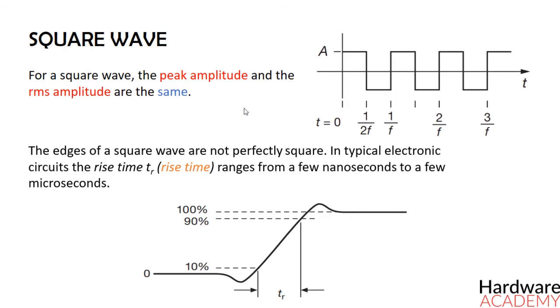And if you strive really hard to achieve a perfect square wave, in this case you will need harmonics of very high frequencies. This is a problem because these high frequency harmonics will generate electromagnetic radiation or pulses of current that interfere with other nearby circuits, causing noise or errors. Another reason that you cannot achieve a perfect square wave, which means a rise time equal to 0, is that the component generating this square wave is not an ideal component. It has its own internal limitations, and exactly because of these limitations you cannot achieve really high switching frequencies.